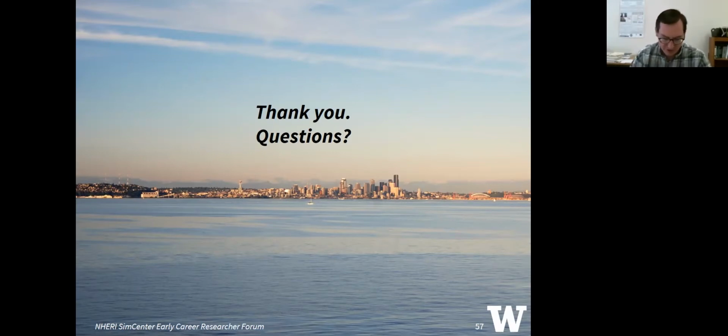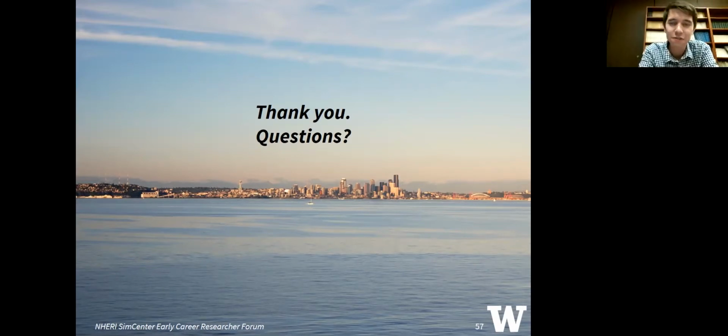So the first question, Andrew, is does the MATLAB API make troubleshooting more or less complicated in OpenSees? So from my perspective, the MATLAB API makes it less complicated. I'm able to go in and see exactly how I've defined the nodes and elements before I've even built the model or even written the model in Tcl. And so, I think because of those plotting capabilities that are native to OpenSees, it does make the troubleshooting quite a bit easier.